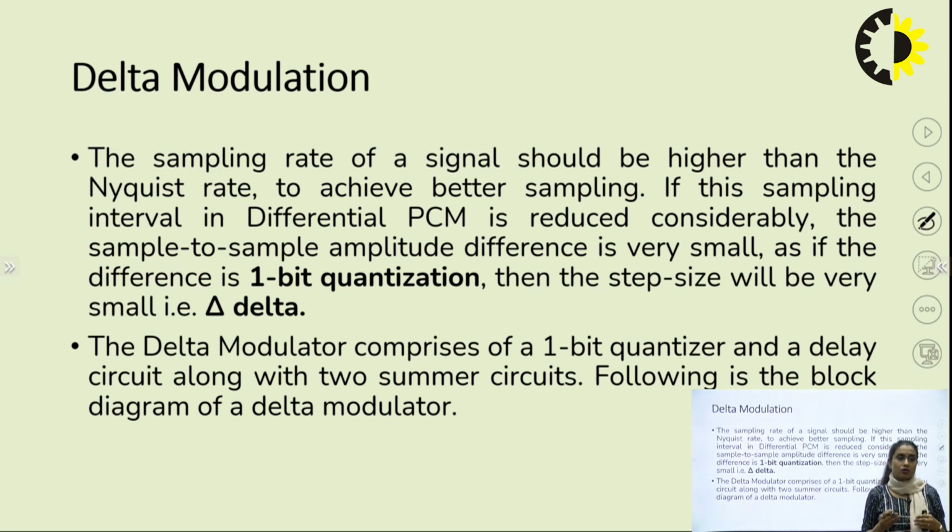And now if I want to go for highly correlated samples, that will help in better reconstruction of the signal. So, let's suppose the very same signal, instead of taking 10 samples, I convert it into 20 samples. So, how many bits will it now be converted into? Instead of 40, now 80 bits will correspond to that particular message. So, 80 bits will help me retrieve the message in its original form in a better, more accurate way, but it will cause congestion, right? My bandwidth required will be too high.